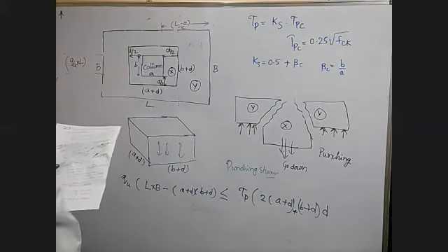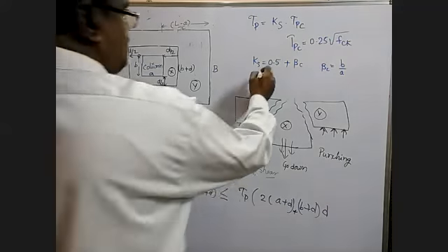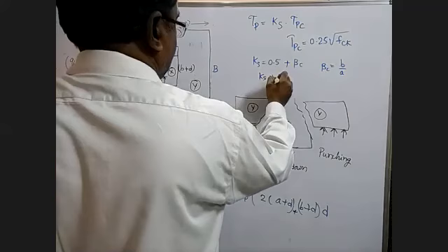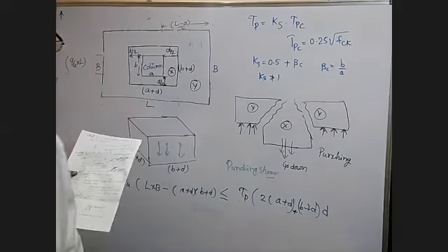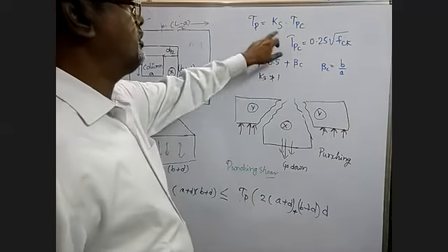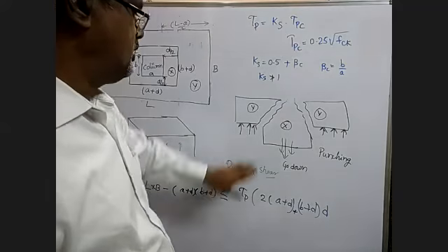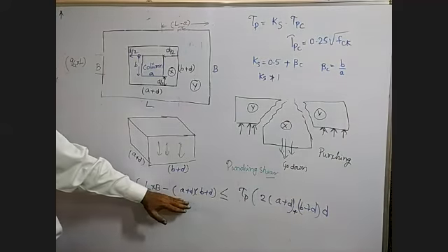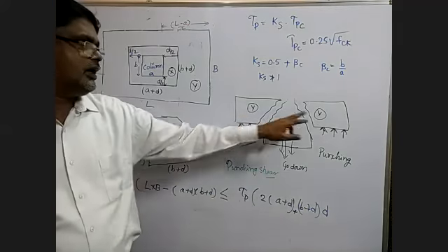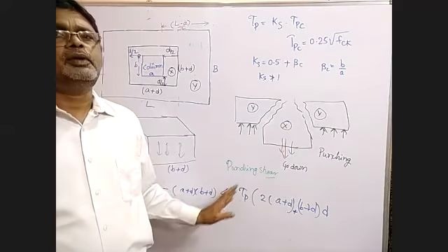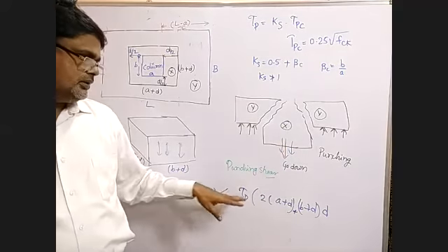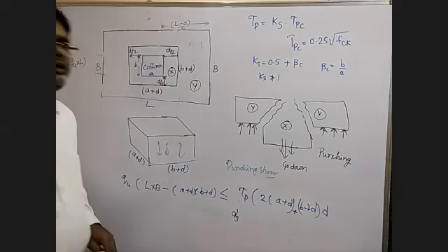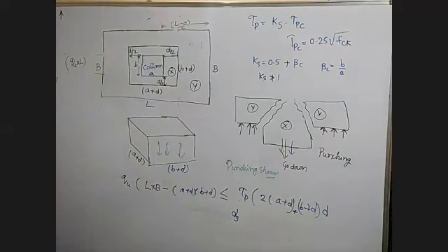Once we calculate these, Ks should not be greater than 1, the maximum value is 1. Giving the Ks value and the tau pc value gives the punching shear, and the x-y value should always be less than the punching shear for failure. So from this you will get the D3 value. From the bending moment criteria you will get D1.